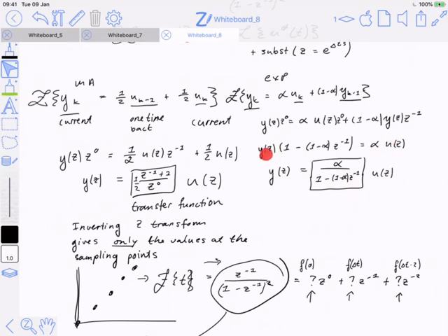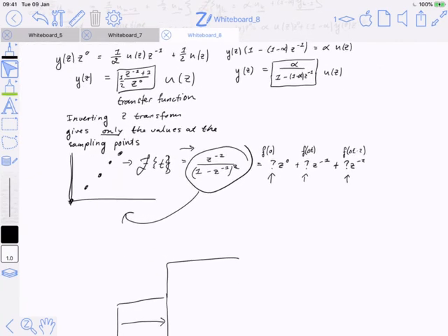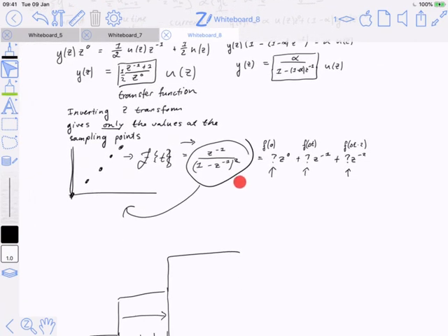If it's much more complicated than this, you'll probably be better off asking SymPy to solve for that transfer function. Effectively, you'll just take this equation and solve it for y, and that'll automatically extract the transfer function for you, just like in Laplace. Then I'm expecting you basically never to do this part by hand.